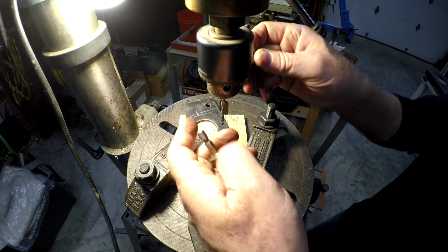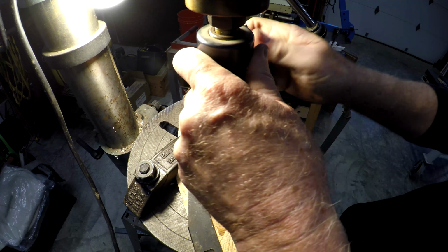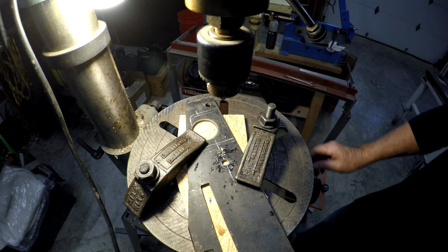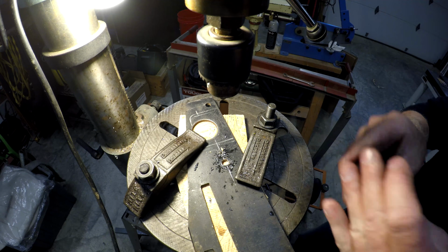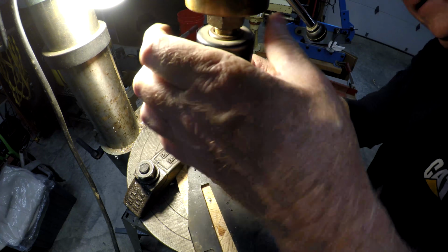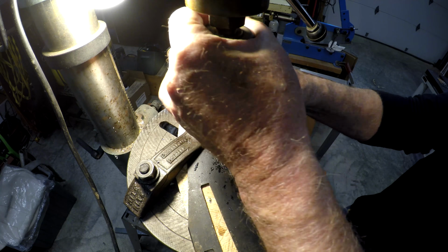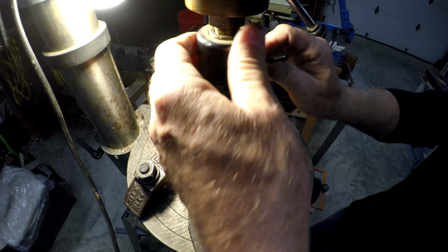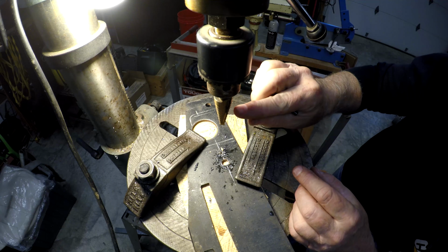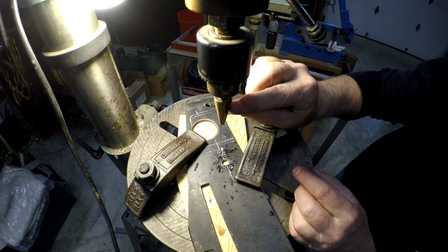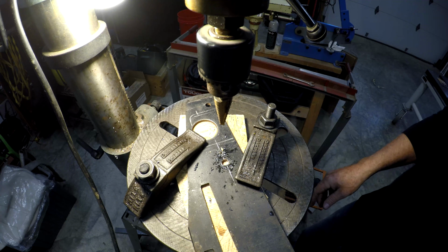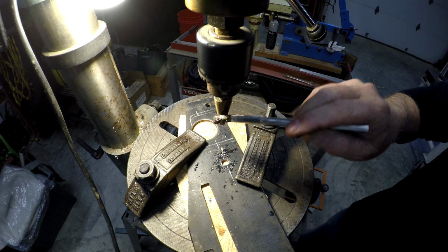For the 5/8 inch hole, I'm just going to be using a step drill. The steps are a little bit shorter than that 3/16 inch, but I think I can either follow it out or hold it in the vise and drill it from the other direction, whatever I can't get through. So 5/8 is this one right there. So it's going to be 3 down from the top. So put a little bit of fluid on there.